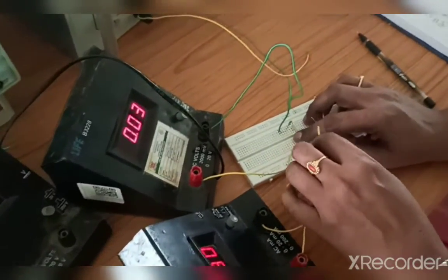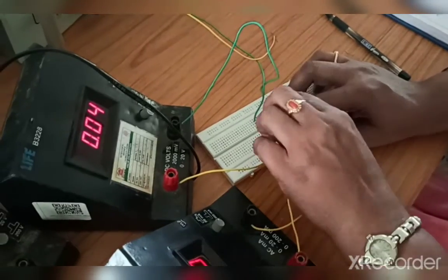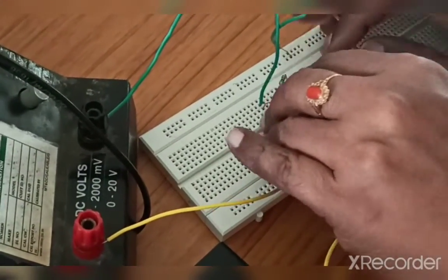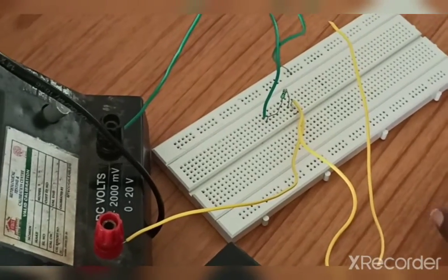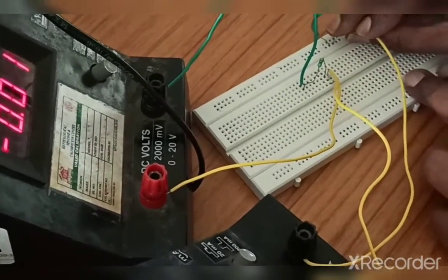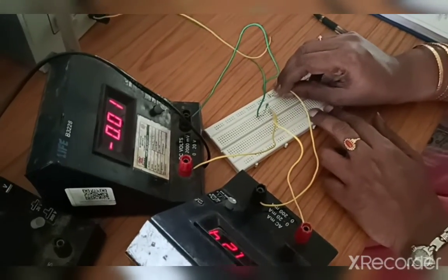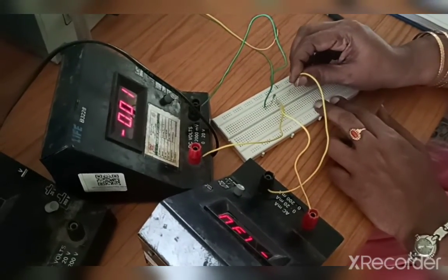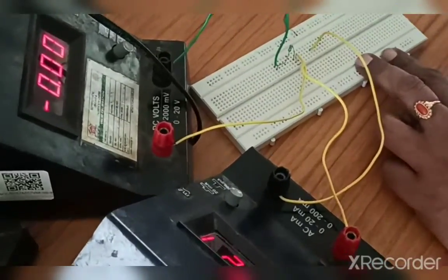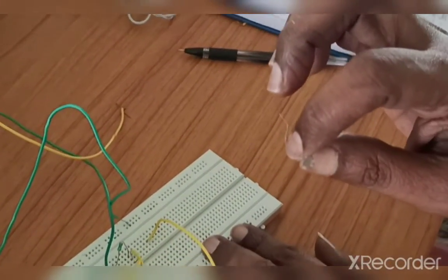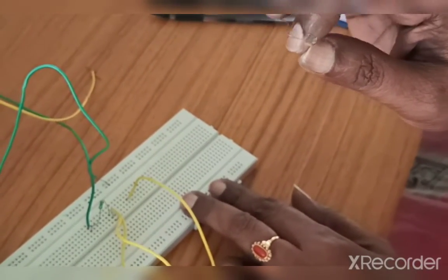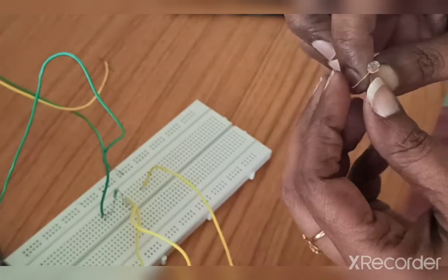Here the design is to design the clamper circuit to clamp the positive peak at 3 volts. We know that V0 is equal to minus V reference plus VD. From that we have to find V reference. V reference is equal to minus V0 plus VD. So that is nothing but minus 3 volts plus 0.7, which is minus 2.3 volt. The frequency F is equal to 1 kilohertz, so T is equal to 1 millisecond.